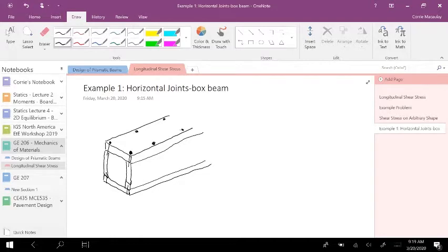So this is a little different than the glued section that we've talked about, right? The glued section, you're going to have bond along the entire length where the glue is. But for the nailed section, you really just have the bond at that nail section, right? Or you're going to have resistance for that plank to move up. The nail is going to try to resist that.